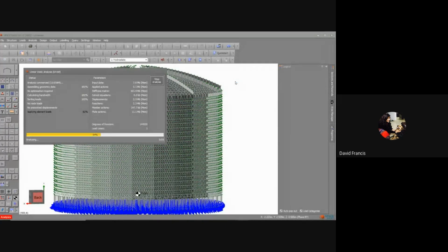And you'll see that it's fairly quick. This is a really useful tool, SketchUp, for connections. I use it a lot, particularly with cold form sections, where you've got weird connections or weird section types as well. Some of those Z's and some of the very fancy ones, we've got them in a library, but they're not. And I also want to check the connectivity, the connection design for them at times.